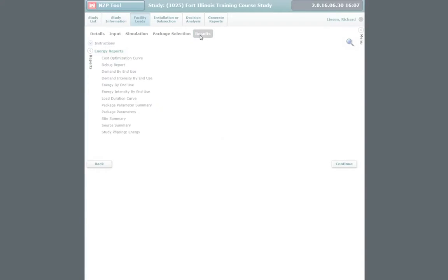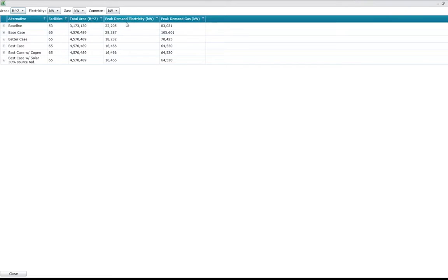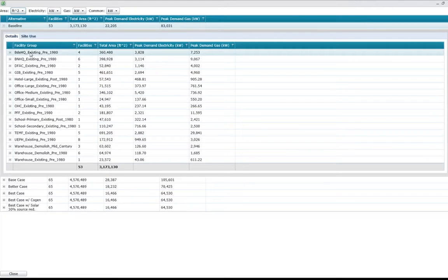So in facility loads, if you recall, Matt had talked about this demand by end use file here, and there's values and costing and things. So they put together this helper spreadsheet and then loaded it with these values, the demands and the peak demands, and this is what sizes your equipment. And so if you look here, you'll see that the cooling equipment is 3,828 kilowatts. This is actually for 4 facilities with 360,000 square feet of area.